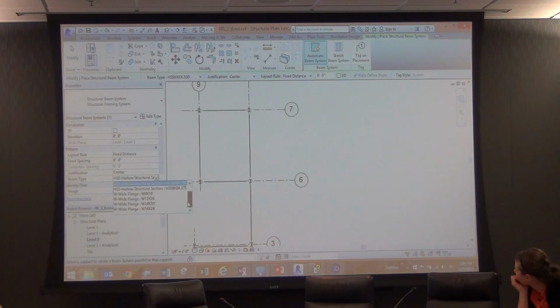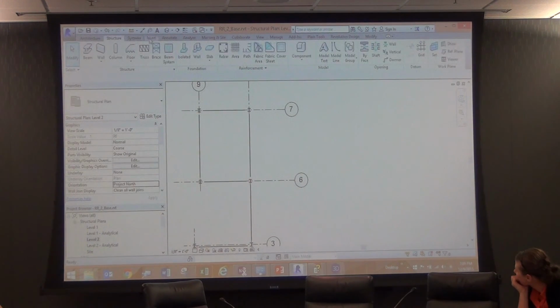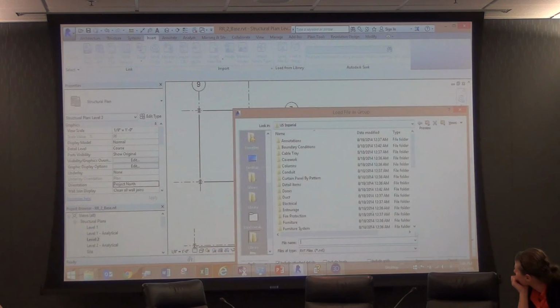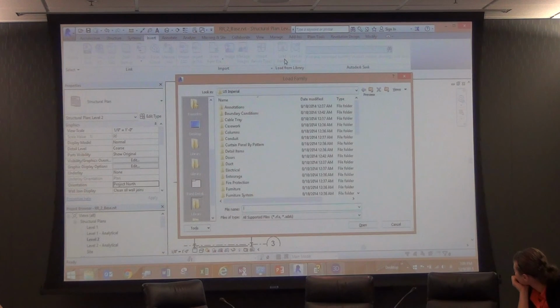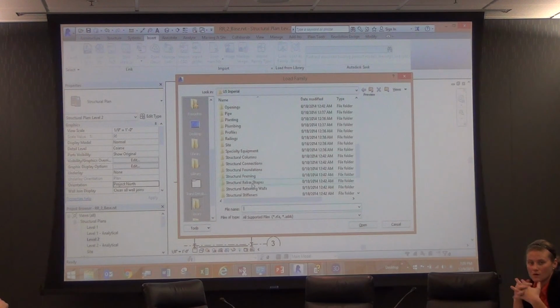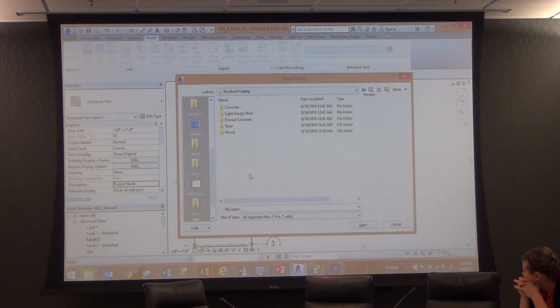I don't know if I have Beam first. I think I don't have any. So I don't know if you guys have noticed this either, but in my experience, the distance between panel points on trusses, open web joists, is 2 feet, but that's not the way the Revit family is set up. So I've gone in and changed the one that I usually use, but it's interesting to me, sometimes I feel like the people that made Revit Structure didn't know structural engineering.